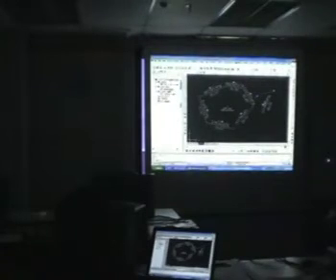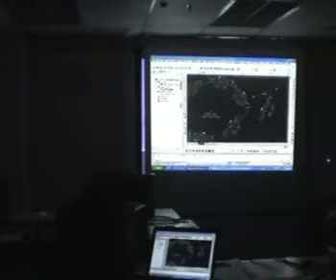Some people like to use dynamic labels because at least they know, okay, if I make any adjustments, the labels are automatically updated with the line. Some people want to use static in case that they say, what if I accidentally move the line and I don't realize it? Because when you move the line, the dynamic labels follow the new position, right? But sometimes it's a mistake. So some of them, they say, okay, leave it as static, so in case I move the line by mistake, they can see, oh, this doesn't match up. I might have made a mistake here. So at least they can correct it if they need to.